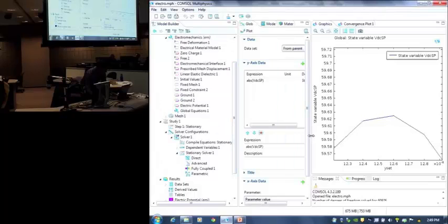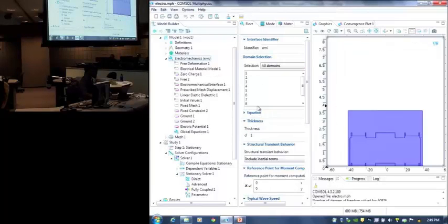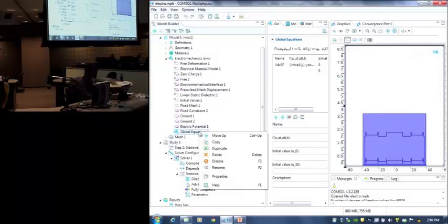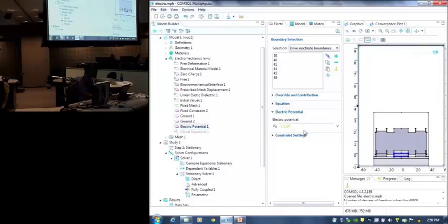Finally, and a rather quicker one, is the frequency response of this kind of problem. How do you model frequency response? For frequency response, we will disable this global equation. We no longer need this global equation because we have a fixed, known DC bias. We'll use the original DC bias, capital V DC.